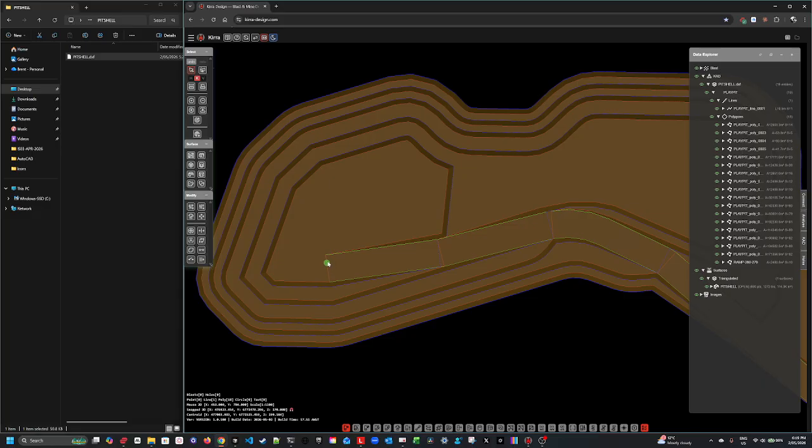Because if I hover over here, I can see down the very bottom of the screen there's a magnet symbol. It's very small to see, but you might see it. It says 270 down in the data text. The alternative is we can use the measure tool. We can click on the measure tool, and we can see our first Z1 is 270 and our Z2 is 280.